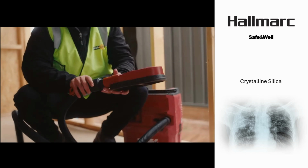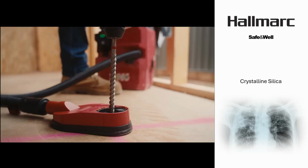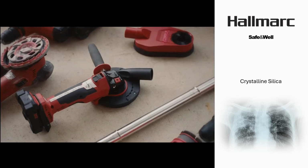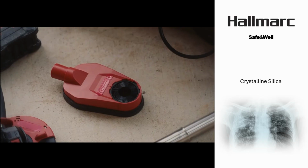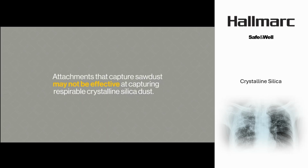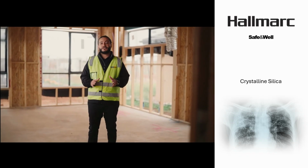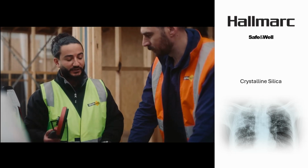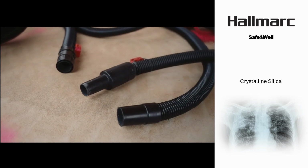The attachment is what connects the power tool to the vacuum. To work best, it needs to be as close as possible to the source of the dust. Attachments are tool and task specific. This means there are specific types of attachments designed for drilling, grinding, or cutting materials containing crystalline silica. Attachments that capture sawdust may not be effective at capturing respirable crystalline silica dust. It's important to ensure the on-tool attachment securely connects to the tool and the hose fitting. All connections should be fitted as the manufacturer recommends. Different hoses are available, and anti-static hoses are a good way to prevent the build-up of static electricity.